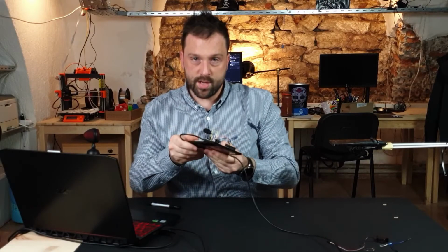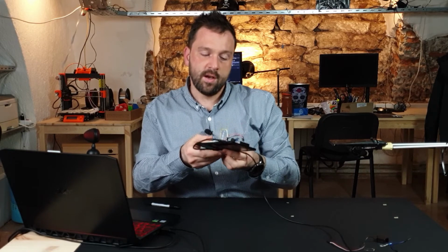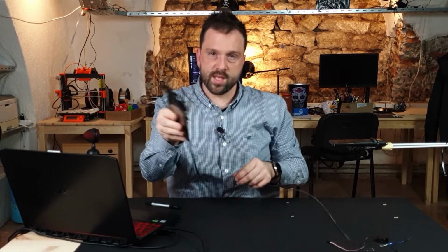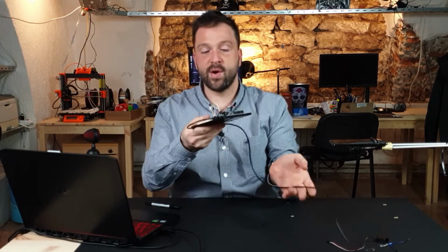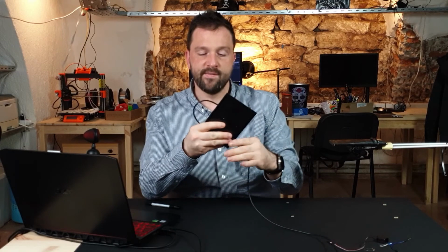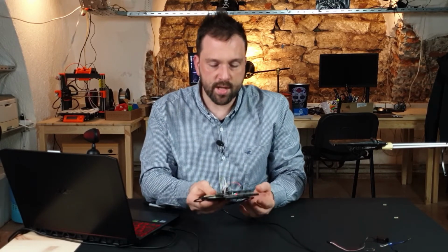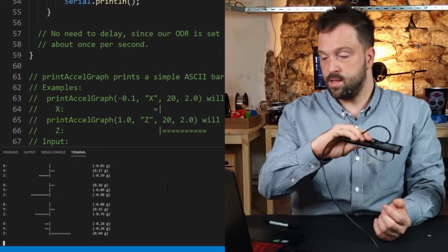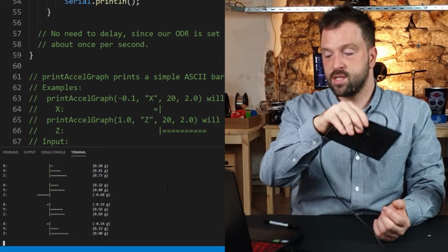While testing the board, it is very important to hold the wire when you're swinging around with the board itself. You can actually break this USB connector here if you do not hold the wire firmly so it doesn't shake a lot. And please do not shake the board, because it's enough to tilt it and you can actually see the changes in the graph.